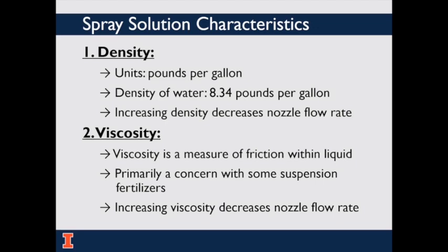Viscosity is another property that affects nozzle flow rate. It's a measure of friction within the liquid and can also be thought of as a fluid's internal resistance to flow. Some suspension fertilizers increase viscosity enough to reduce flow over 10% compared with water. The effects of viscosity can be compensated to some degree in the same way as density, though it may be necessary to slightly dilute the solution with water to get proper flow.